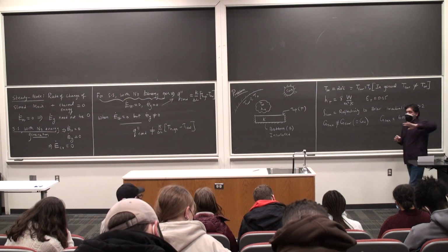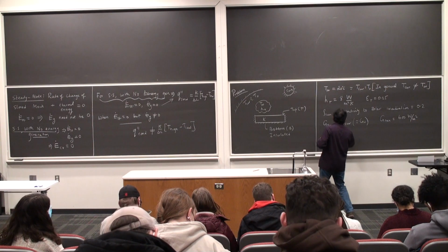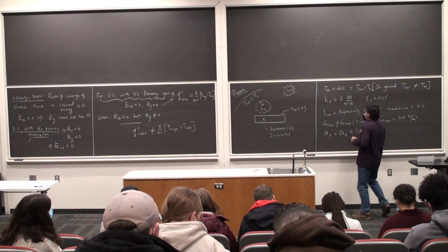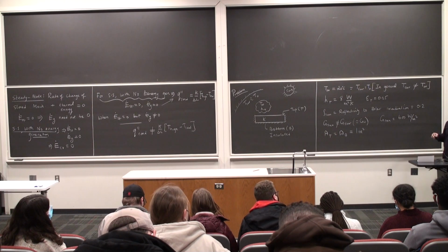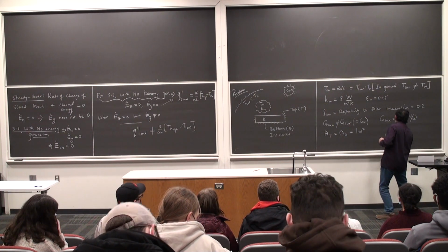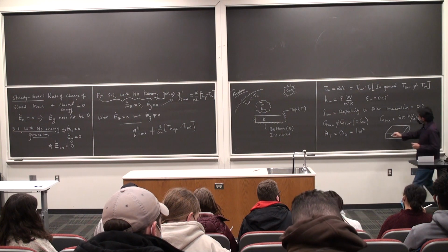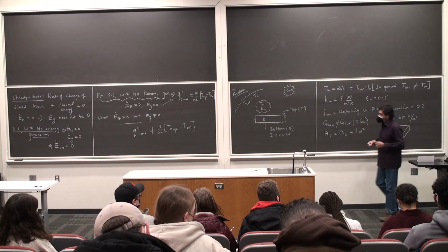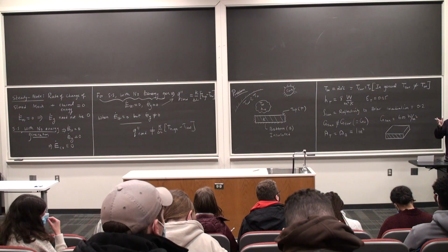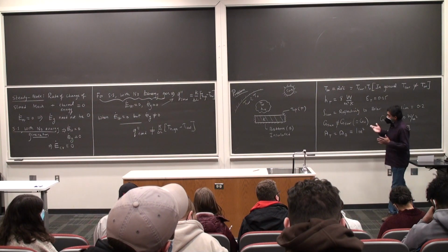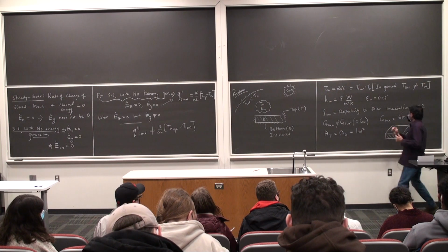The area of cross section that is available for heat transfer is going to be 1 meter square. So area A of the top, same as the bottom, is 1 meter square. Typically when we talk about area, this is the area of the surface that is interacting with the ambient fluid and the surroundings. For example, if I draw a 3D view of the slab, this is the view that you are seeing on the board. This shaded piece is what you're seeing. The area that they are talking about, which is available for heat transfer on the top surface, is the area that is projected out of the page.